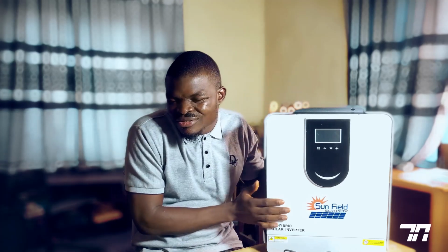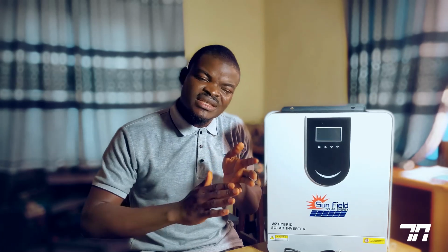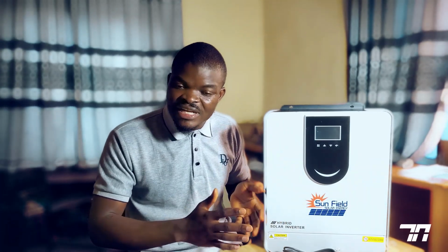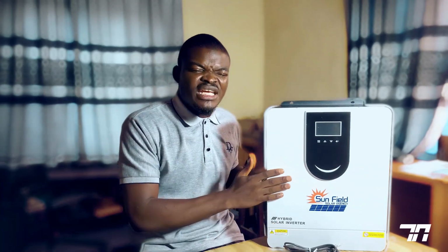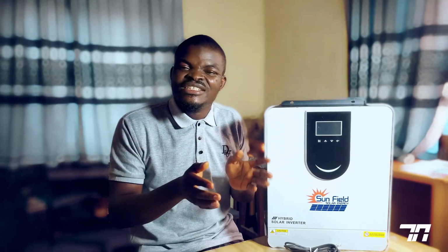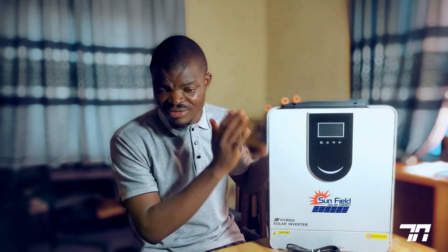So that in turn gives these inverters an advantage, which makes it be able to work without battery. So when you connect it to solar enough, that's why it's high voltage. So as long as your voltage is above 220, like you are generating like 250 plus about 300 volts, it will be convenient for it to change you to solar, just as if it's changing to NEPA, and you need to leave your battery alone. So that's another advantage of high frequencies.